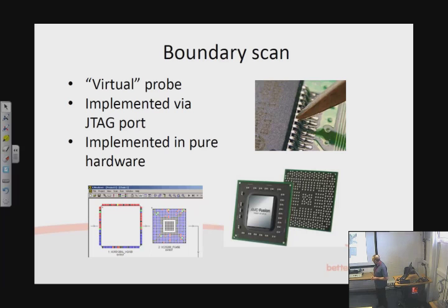And so the wonder of the JTAG port is that because, of course, you couldn't get any software running potentially, because if, for example, you hadn't soldered your chip down properly, so the clock wasn't working or anything like that, there was no use trying to get any test software running on your chip because it wasn't there yet, or in fact the chip might be so simple it doesn't use software. So the idea of the JTAG port is entirely clocked from the external equipment.